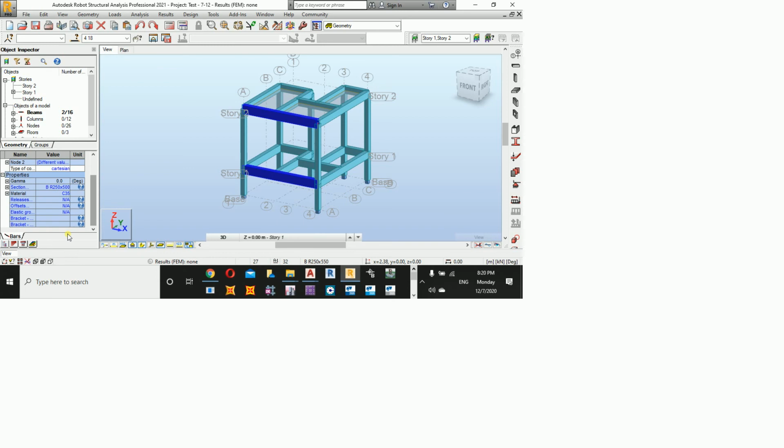The same thing will go for the other beam. This one is having 5.5 meter. That's why the depth is high. We'll choose the other one as well. Now we are going to put it how much? 250 into 550, right? Are we okay? Now I want to confirm whatever I have done is correct or not before going to the design, which will start tomorrow, before doing the loading and whatever.